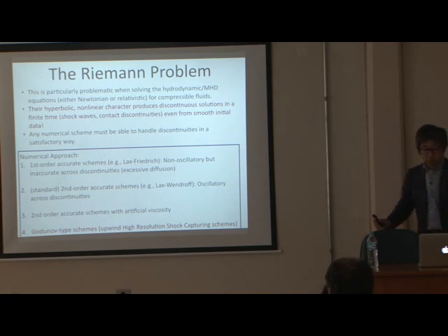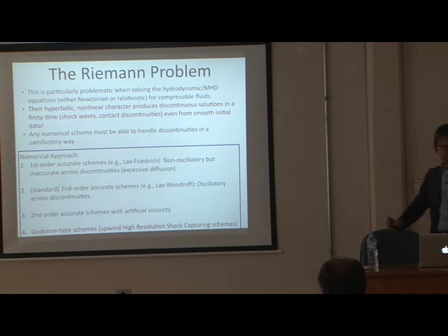Okay, so this is particularly problematic when solving the hydrodynamic equations for a compressible fluid. The hyperbolic system has nonlinear characteristics that produce discontinuous solutions in finite time, like a shock wave or contact discontinuity, even from smooth initial data. So any numerical scheme must be able to handle the discontinuity in a satisfactory way.